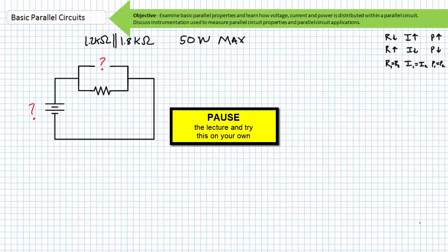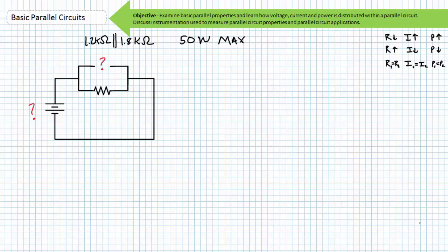Think about current and power distribution within a parallel circuit. Think about different permutations of the power formula and how they relate to Ohm's law. Recall that within a parallel relationship, the smallest resistor draws the most current. Given voltage across elements hooked in parallel is the same, and power, being the product of voltage and current, it is therefore understandable that the smallest resistor within this parallel relationship would dissipate the most power.